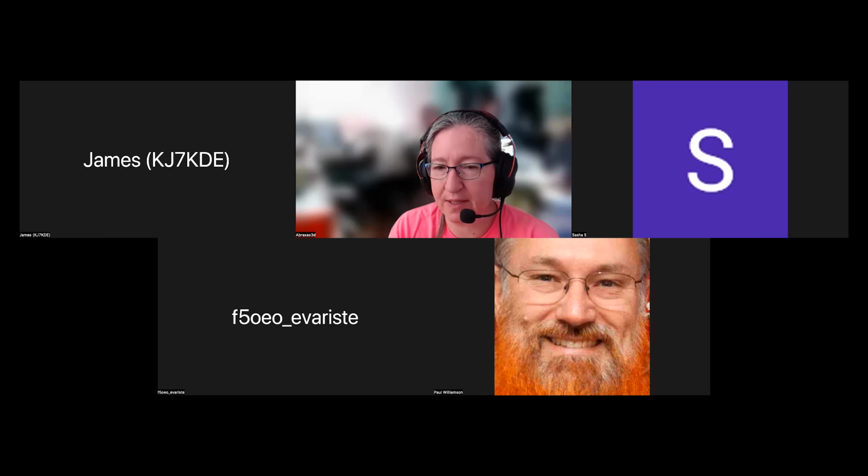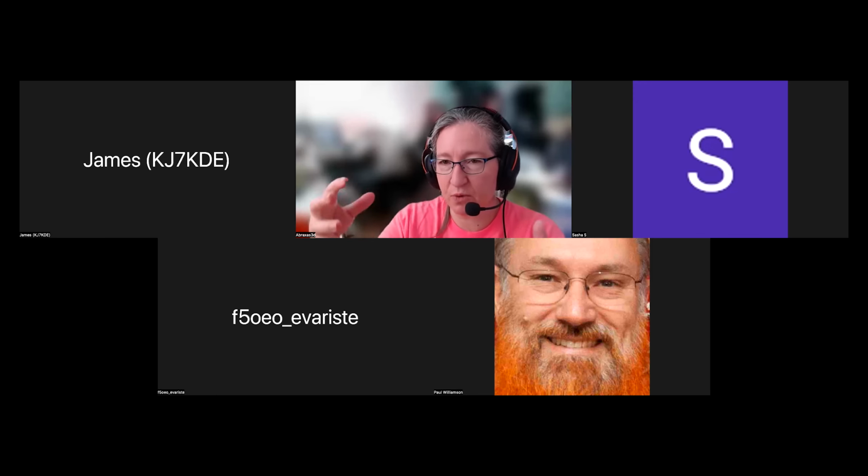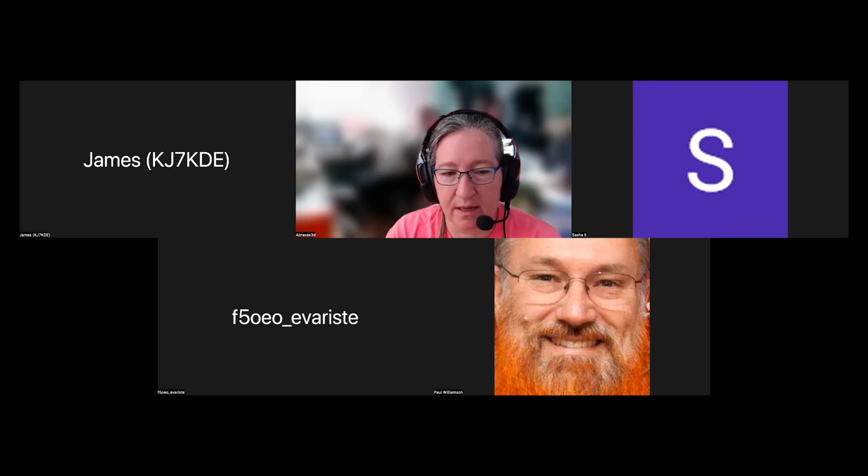Attached to it is something called an ADRV9371, the 9371 RF SoC from Analog Devices, and that's their development board. These two boards fit together, and they make an FPGA radio development platform. So that's where we start and get the hardware working.